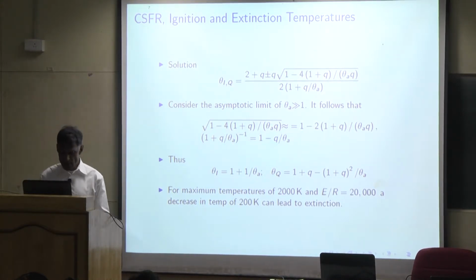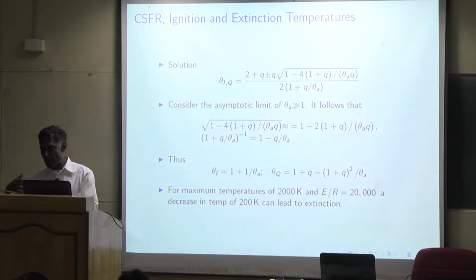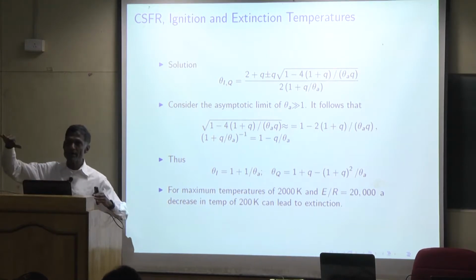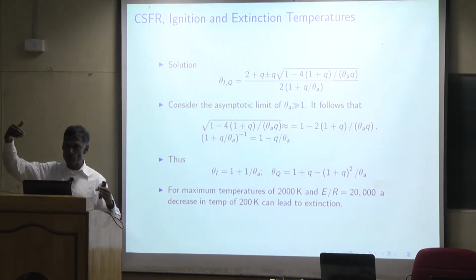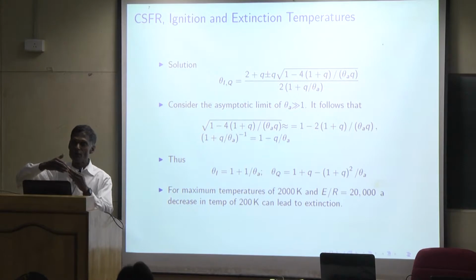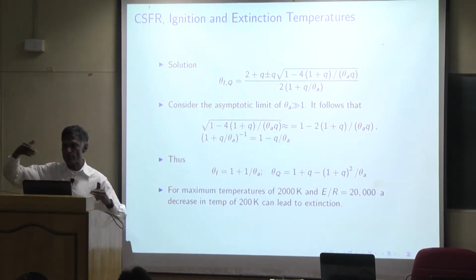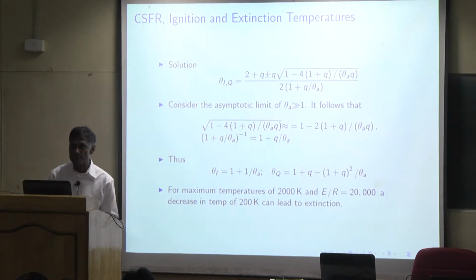If it does not, then of course that's a stable solution. If you put these equations in what's known as a phase space, analyzing the phase space, you get what is known as a saddle point singularity, an unstable nodal point singularity, and a stable nodal point singularity. In an unstable nodal point singularity, all the integral curves will move away. In a stable point singularity, they all will move in. So you can analyze the stability problem that way and see whether the integral curves go out or come in.